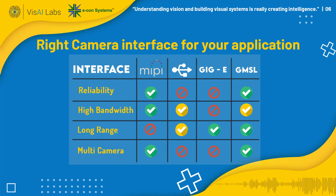When it comes to GMSL, GMSL can be used for a longer distance. When it comes to MIPI, it can be supported up to 30 to 50 centimeters. But when it goes for longer distance, like applications like fleet management, you may not be able to use MIPI interface right away. You will have to serialize the signals. You can use GMSL.